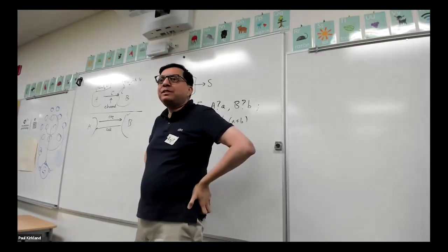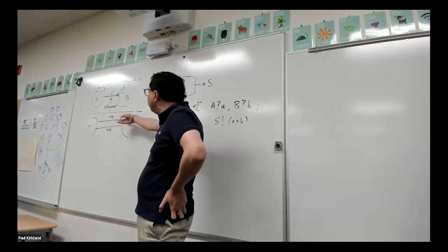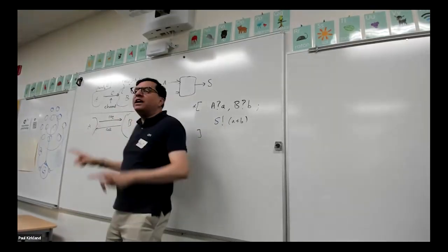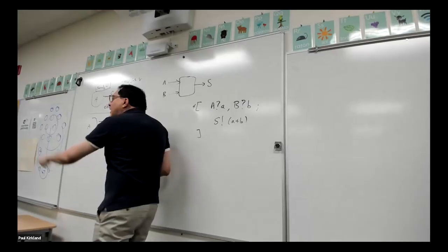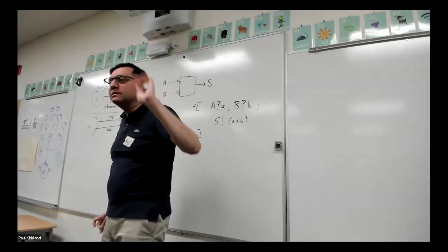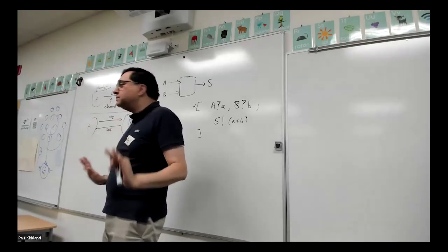So this is completely combinational logic now? Or no, there will be state holding gates, right? Because you're going to have to wait for the request probably. So there will be some. Usually on every cycle of logic, there is at least one state holding gate, unless you have a ring oscillator. It's a special logic circuit. Anyway, it doesn't matter.